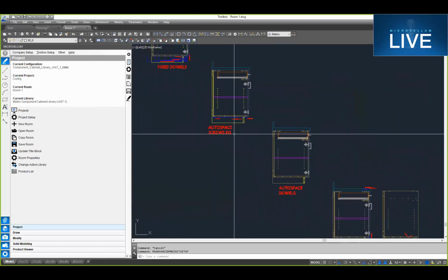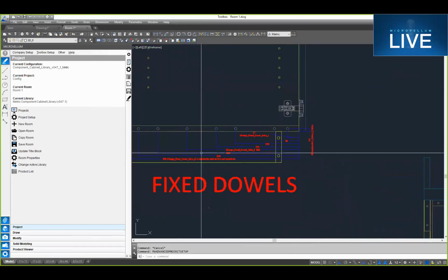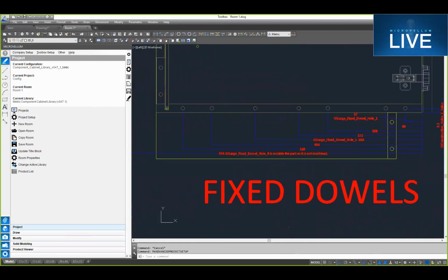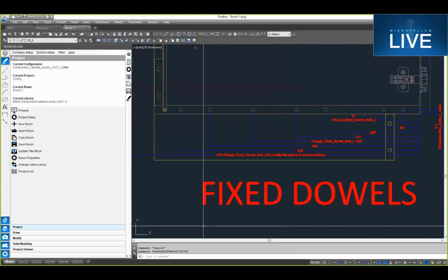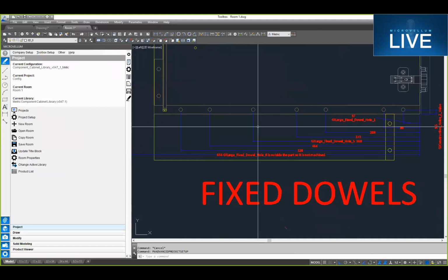And then we have our fixed pattern. And so looking at this particular cabinet, we have a fixed pattern for that. And so this method works really well with a non-CNC horizontal boring machine, where we might have fixed heads on there and we insert drills into our 32mm boring machine at certain increments, and those are always fixed. They never change. You just put the part up against the fence and you drill that part regardless of its size. It just puts the drills that hit into the parts. And so that works well for a fixed head drilling machine.